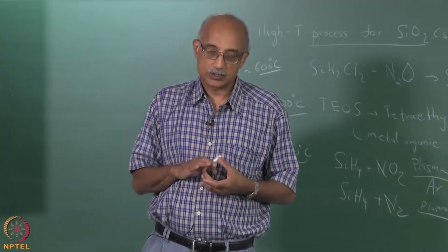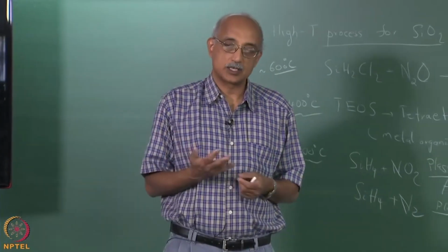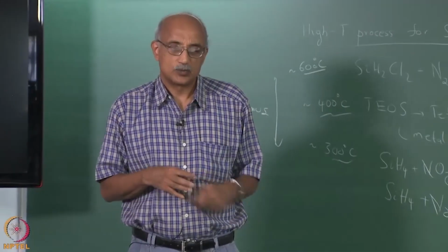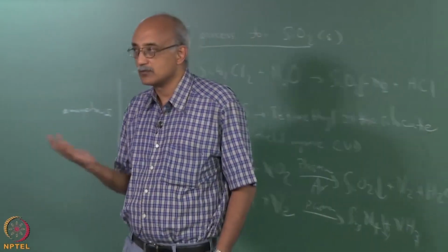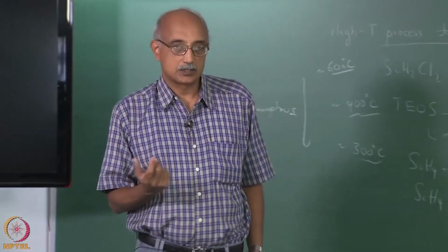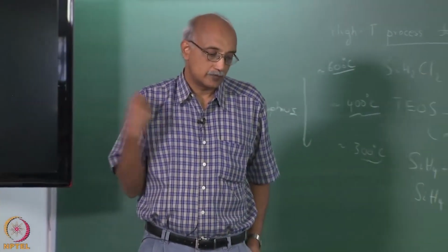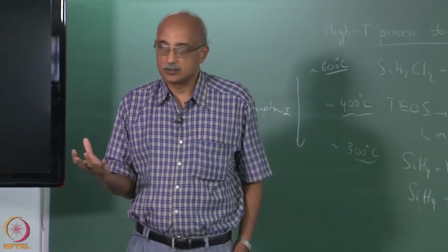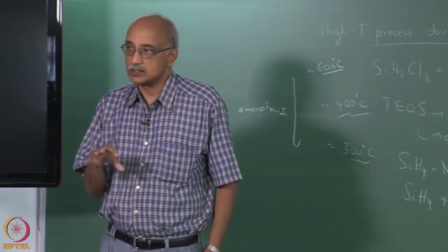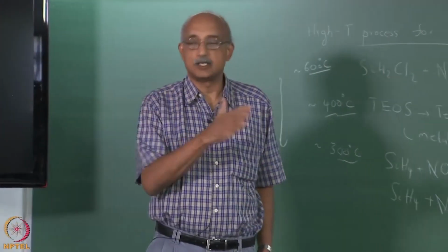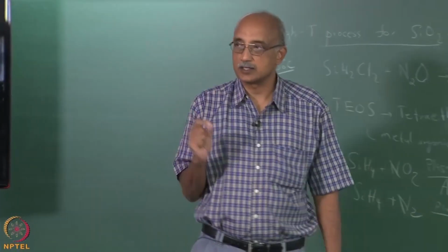So, metal deposition also is typically done under low pressure CVD conditions and hot wall conditions. The most commonly deposited metal is tungsten. Tungsten is a material that lends itself to CVD because it is a very reactive metal. So, in a CVD system, if you introduce a species containing tungsten, the tungsten will quickly react with whatever elements are present in the system and form a whole family of vapor phase compounds. And the whole trick to actually running a CVD process is to have a highly reactive system.